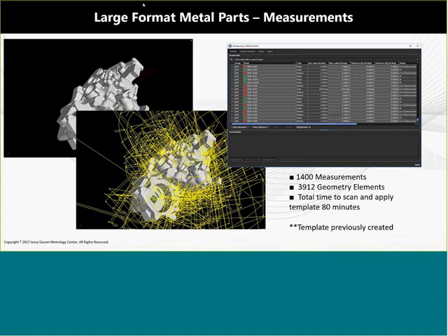Not only that, if anybody has adopted PMI, or part measurement information, in their CAD files, that can be directly imported and overlaid on top of the CT data set as well. In this particular example, the part had over 1,400 measurements with 3,900 geometry elements. And the total time to apply that took 80 minutes once the template was set.